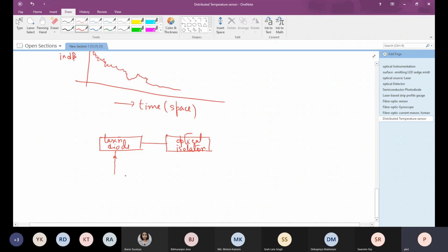Because with a high power pulse laser, though we can generate a switch, making a frequency modulation is difficult. So a separate frequency modulator is kept in a high power pulse laser. But a laser diode having, say, roughly 1 watt of power can be directly modulated.